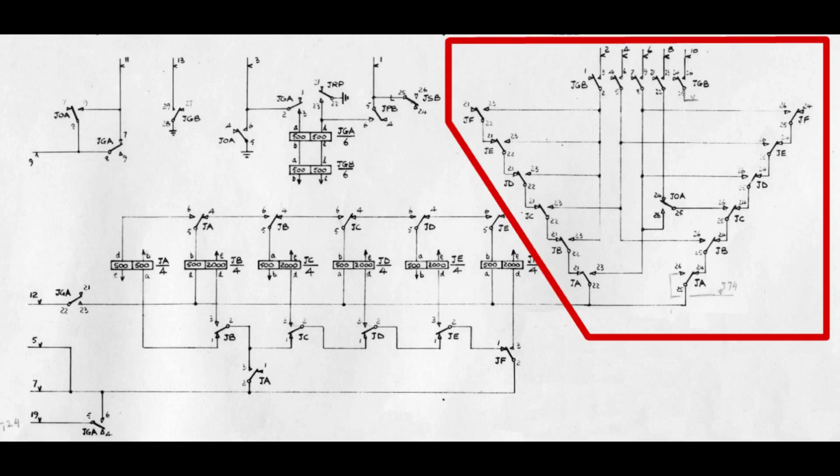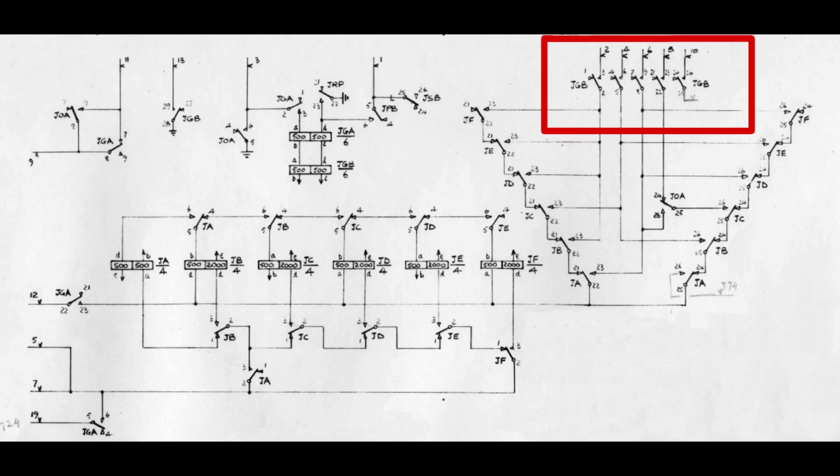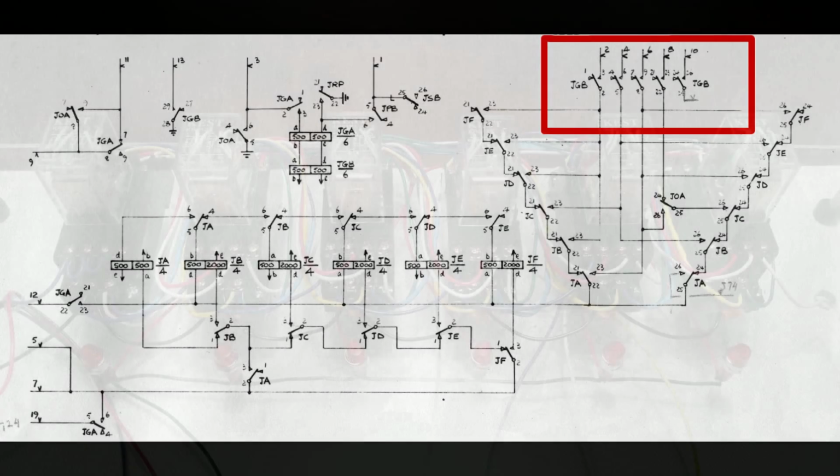Turns out that on the punch tape, commands are preceded with a space character to indicate the command follows next on the paper tape. So the actual contents of the ROM are the characters space 03101. The last section highlighted in the schematic shows an additional post office relay that connects the ROM section to the 5-wire input system that was described earlier. Once the commands from the ROM have been sent, the relay disconnects the ROM section.